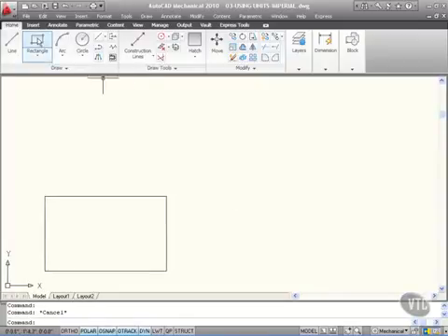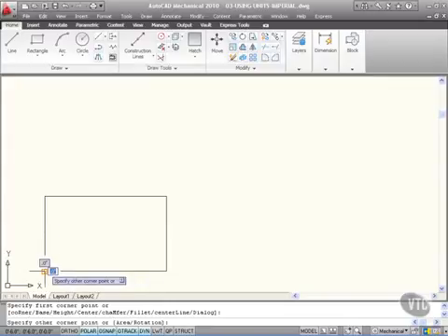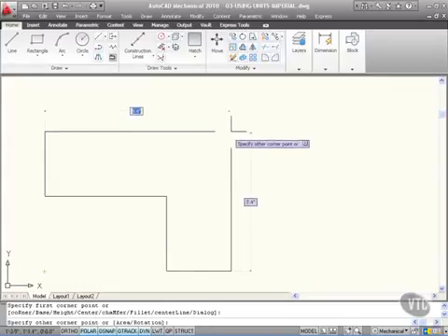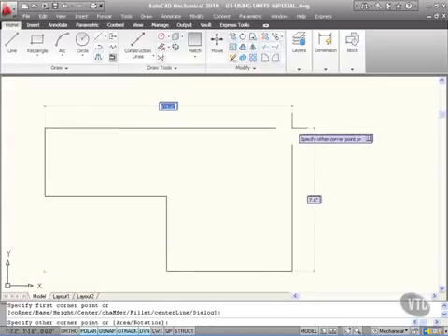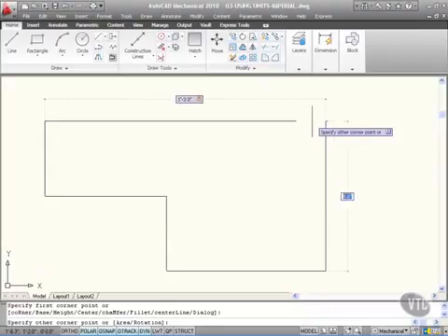So now I go to rectangle again, and I'm now going to click on this corner here. I'm going to use the object snap, the endpoint snap. So when I hover there and click, like so, and come out now, can you see, look, as I get bigger there, it automatically goes to that 1 foot, 2.3 inches in the X direction. Now to type that in, I'd put 1, and then I put that symbol there like that, then a dash, and then 3 inches, like so. As soon as I press the tab, it picks up that it's 1 foot 3 inches.